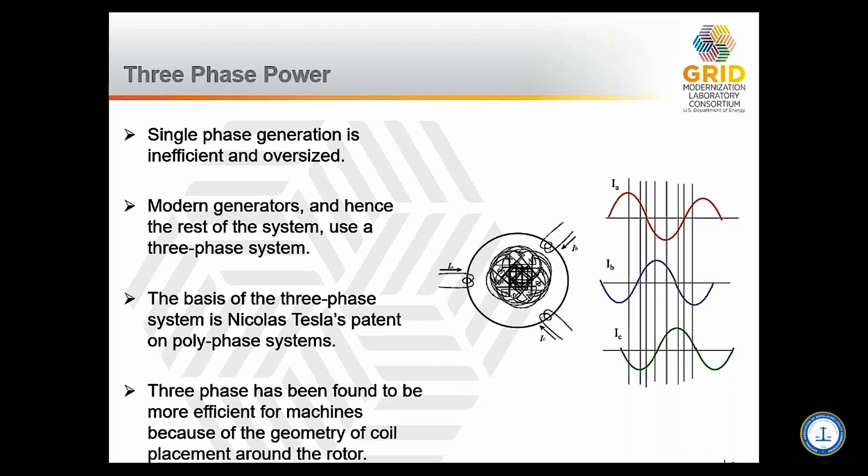And what you'll see here is another simplified diagram where you have the rotor spinning in the middle, and then you'd have 3 sets of coils. And what you'll end up with are 3 independent currents that are being driven by the voltages. Now, an interesting aspect of those currents, because you still have a single magnet in the middle, or electromagnet, is that the phases of those voltage waveforms are out of phase, meaning that the north face of the bar magnet in the middle can only be aligned with phase A, B, or C at one time. So with 360 degrees in a circle, these voltages and currents are 120 degrees out of phase.